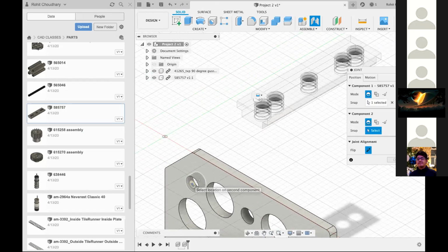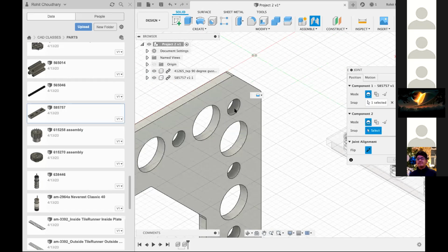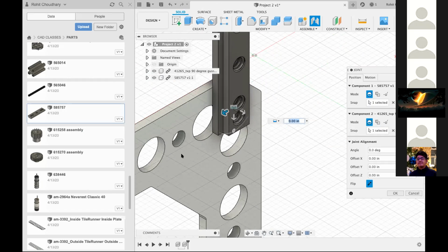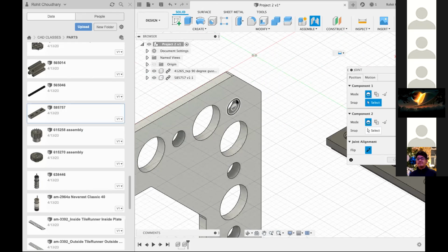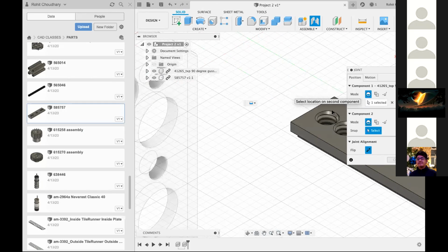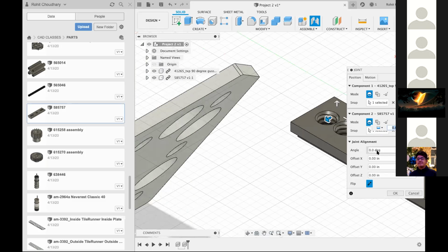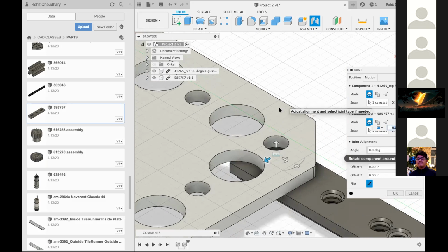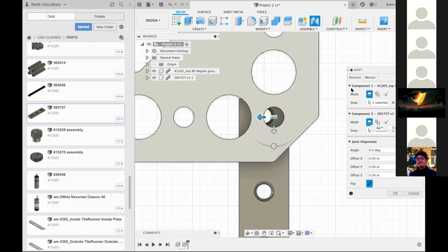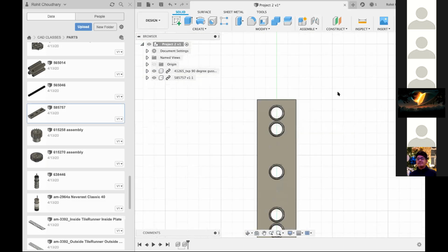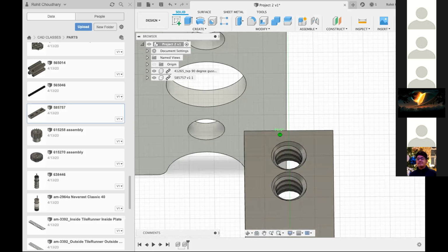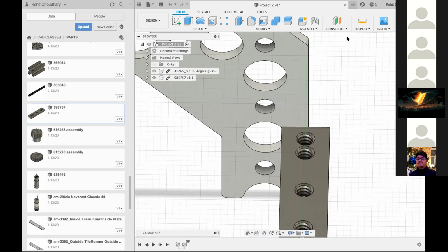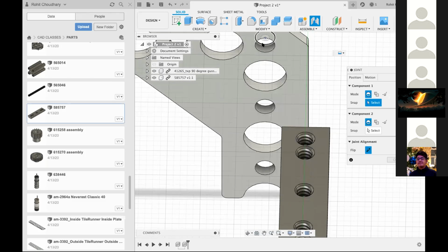So if I do that, and let's say my second component is this one, you'll see that, okay, one second. Let me do this one to that. If I choose a circle and my second component is just a point like this, then sometimes it becomes really finicky, and it just depends on where you selected your joints from. What helps sometimes is to zoom in or try it from a different angle. So be careful of that when you're doing joints.